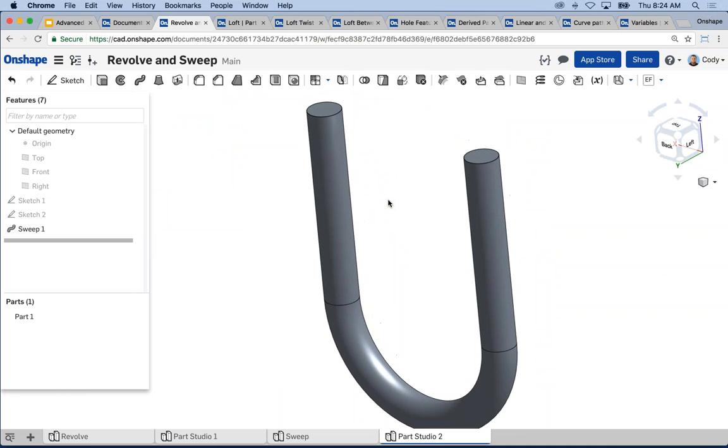Okay. So again, profile and path, the big tips to keep in mind, make sure that in general, you're going to probably need to insert a plane normal to the end of your path, and then attach that profile to the path either using coincident or pierce constraint.